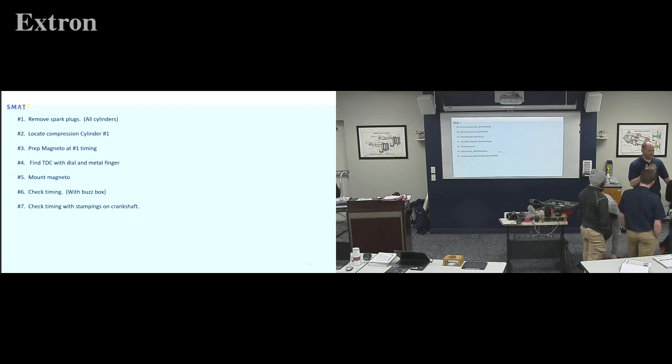Well, you go too far. Yep. All right, so to answer your question, technically, when we're going this way now, we are after top center, however many degrees. Now we're at bottom center. Now we're approaching top center again. And the sanity check is 37 before 38 before top center. So the sanity check is, okay, good, I hit it.